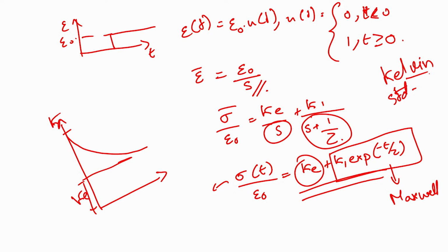We have a lot of models like this which are used to depict the mechanical properties of tissue using dynamic testing. Depending on the tissue behavior, one model might fit better than another. Different materials, even different types of tissues, will have different correlations with different models. A diseased tissue might be better fit using maybe a Maxwell model, I'm just saying, not really, but maybe a normal tissue will be more towards the SLS model.